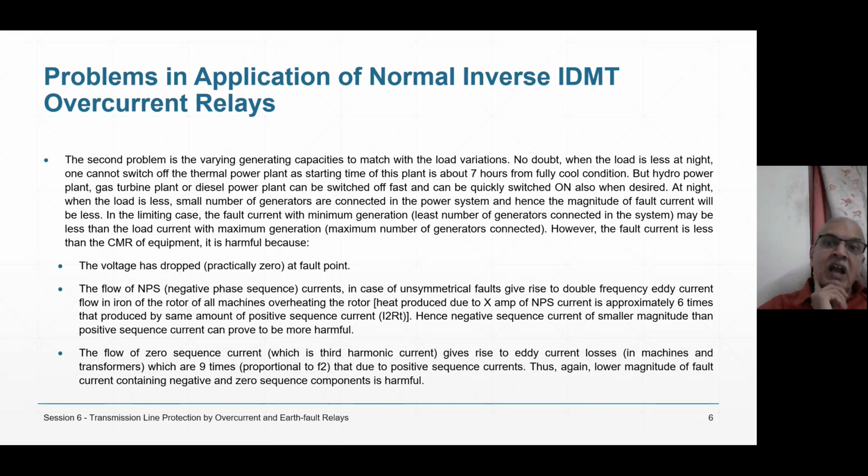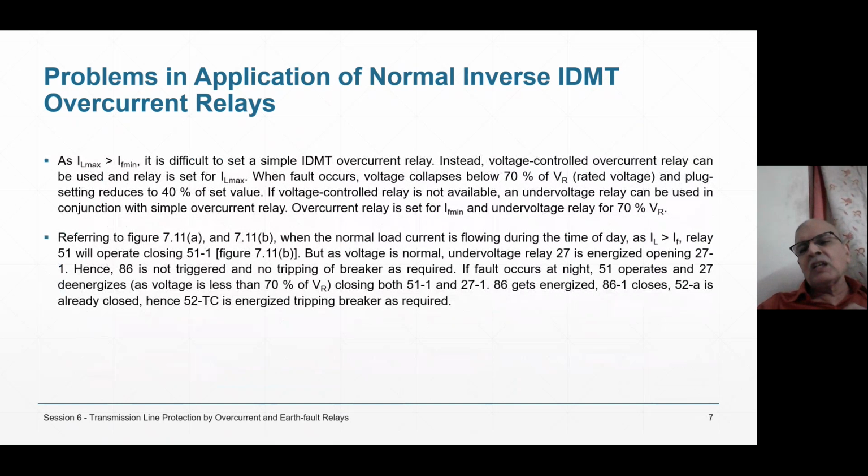So the problem is how to sense a fault current that is less than the load current. In the relaying world, a voltage controlled overcurrent relay is available.